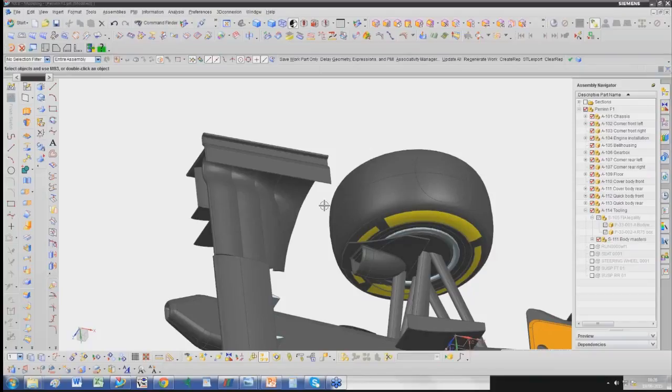But to create that static pressure, you need to understand what total pressure you have around the car. You know, what flow, energy, what velocity is going around. So you need to look at the total pressure. And there is a link between the two, obviously. We talked about Bernoulli, we talked about velocity increasing under the wing and static pressure dropping. So that link exists. So you need to look at both.